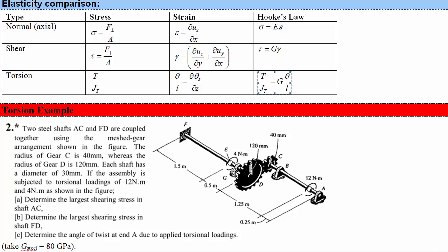And because the torques are actually 32 Newton meters in the negative direction and then 36 Newton meters in the negative direction here, this gear rotates in the negative direction, in the direction that I'm showing here, which makes this gear rotate in the positive direction by 3 times as much. The gear ratio working in our favor there, or at least as long as we want more rotation anyway.